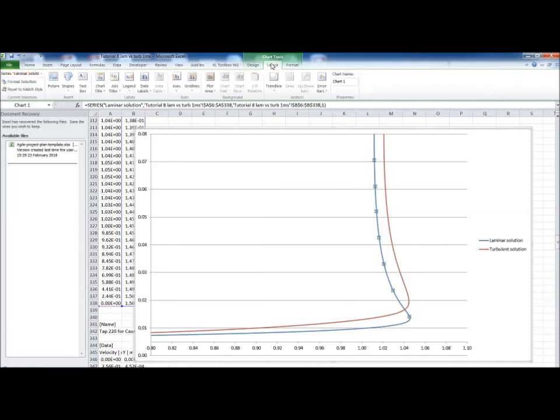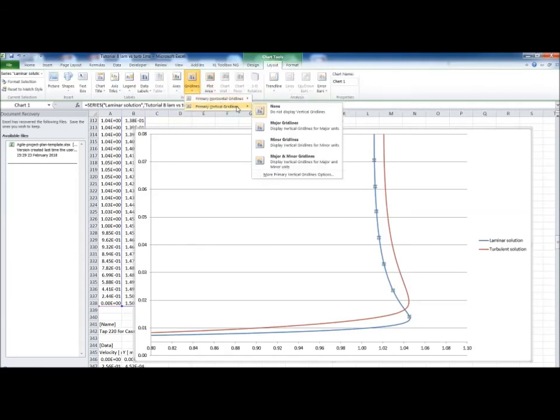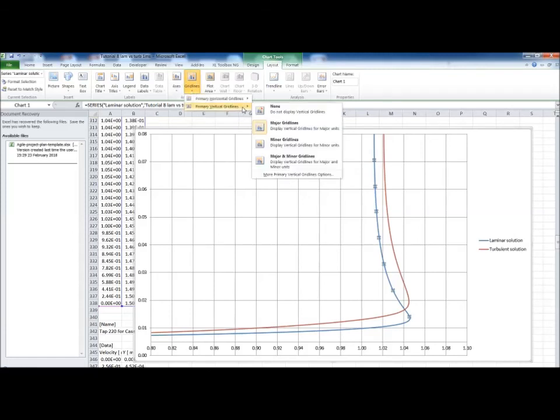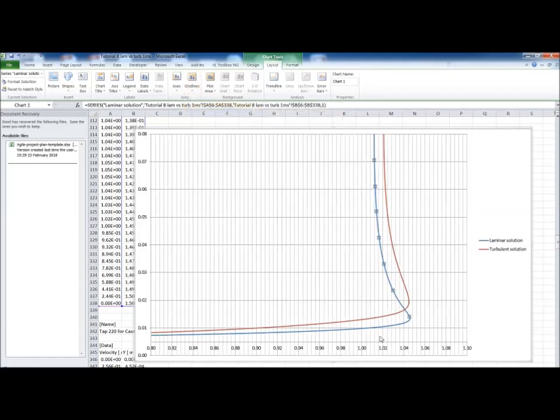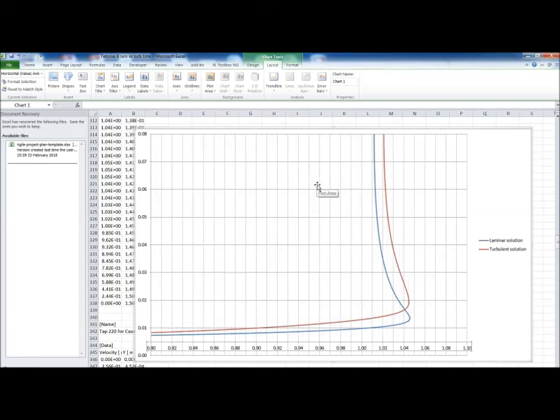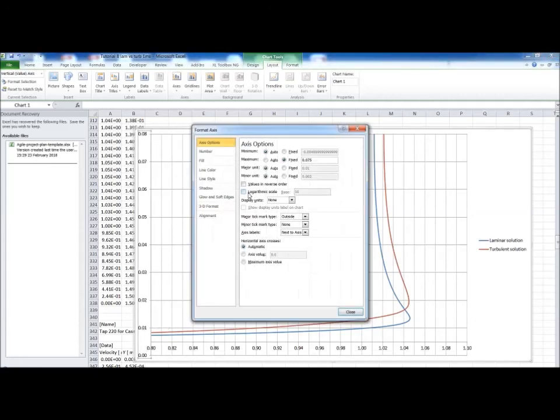So what we need to do is plot maybe some grid lines that will show it clearer. Primary vertical, major, grid lines, primary vertical, minor. So let's do 0.02 and fix 0.01. So that gives us this point here, and then also we're going to do this as fixed 0.